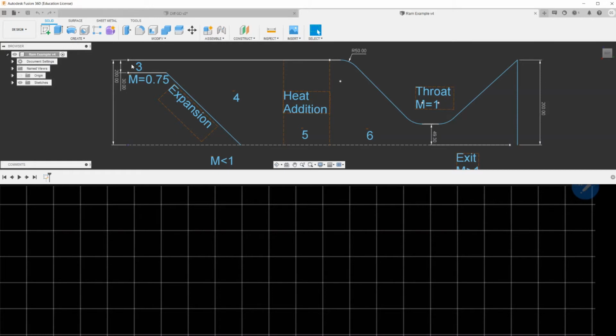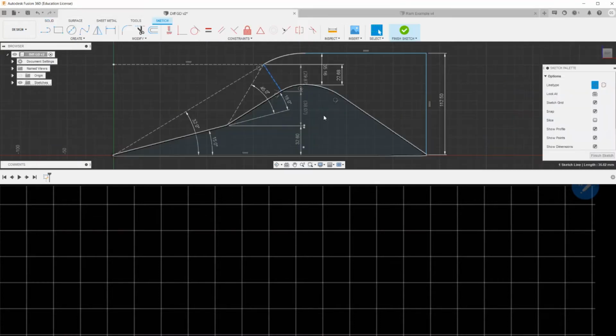Because flow is subsonic in this region, it means that increasing pressure inside the combustion chamber by constraining the throat, you at the same time increase the pressure everywhere in this section, right, in the subsonic part of the nozzle, including the subsonic part of the diffuser, right? So when you have too small a throat, the mass flow rate is limited, and this limited mass flow rate creates big back pressure here.